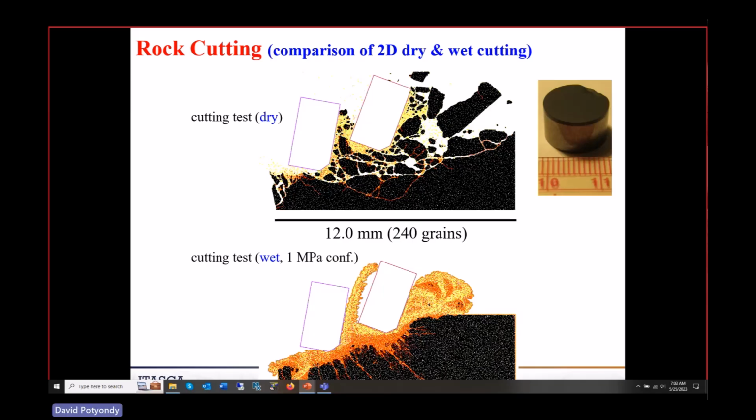When I did this initial work back in the early 2000s for this guy at Hughes Christensen, he ran a bunch of these models and just looked at animations, and he suddenly was like, oh my God, you've got broken material. This is material flow. This is frictional granular material. It's flowing around the boundary at the bottom here. That's why the shape of this has such a big impact. And so that was an interesting thing. It's one of those things where you have a model and then you see things with it that you wouldn't necessarily have thought of to begin with.